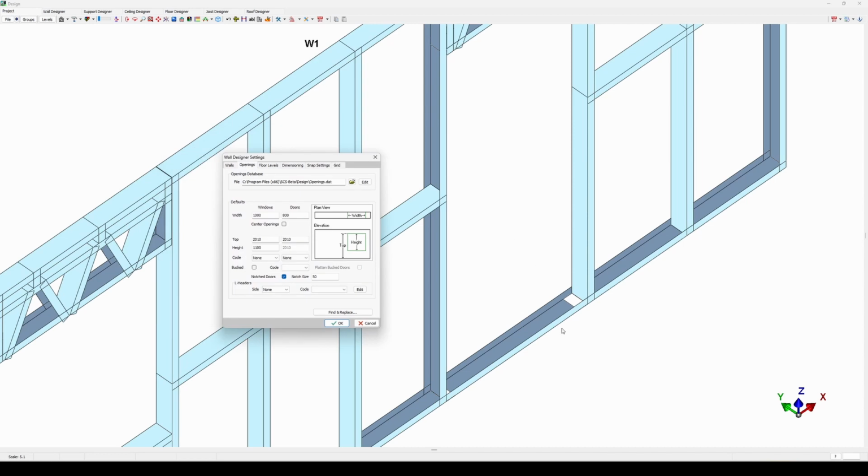Just a side note on the notching of your door frame right there is to only do this when you're doing on-site assembly. It does make it easier when you do these cuts on site, and also for transport reasons you might want to exclude those notching options as to strengthen the bottom plate a little bit more, just for the purpose of keeping your frame from bucking or bending while they are being transported to site. So if you're transporting this frame assembled to site, make sure to keep the notching off.